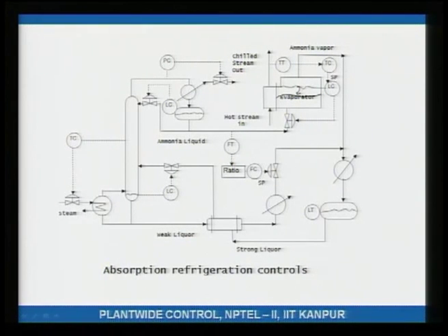Since less vaporization will occur, the amount of water needed to absorb that less ammonia should also decrease. Let us say it takes 2 kilograms of water to absorb 10 grams of ammonia. Because the ammonia rate is going down, you should also reduce the amount of water that is going in.